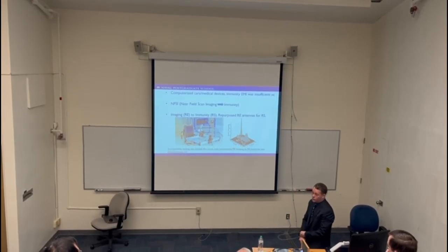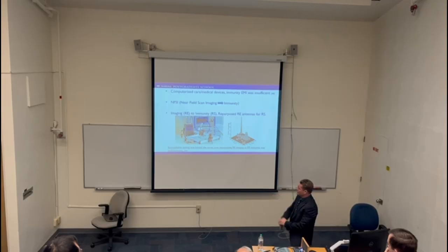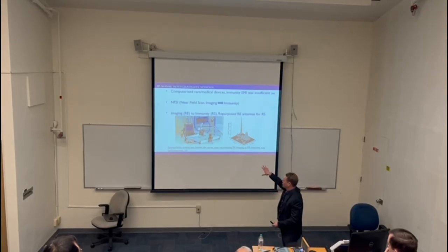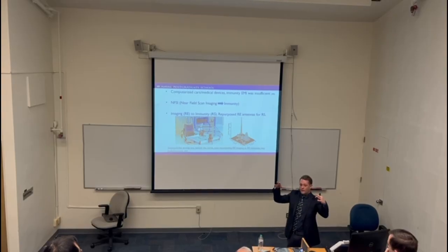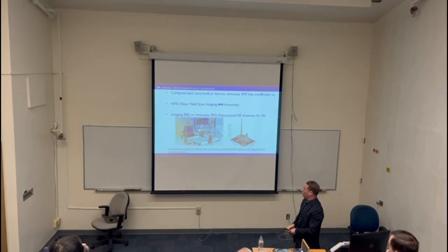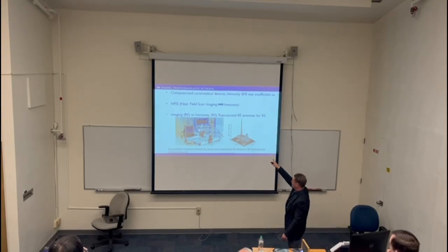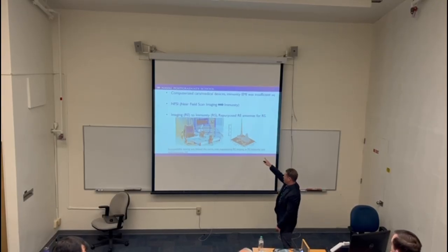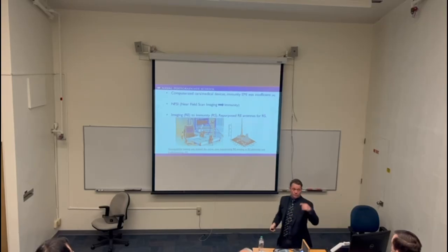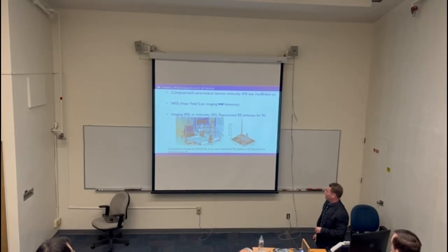So they actually started to repurpose some of the devices such as near-field scan imaging. The imaging was literally scanning over a surface, looking at, okay, what is my radiated emissions across this XYZ platform? And they mapped it out. You can see this is actually a susceptibility plot, because, as I'm going to get to, they repurposed this from the reciprocity theorem of antennas.